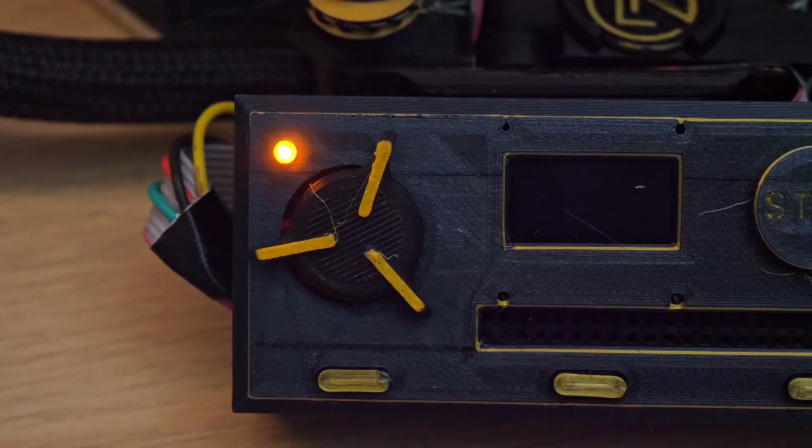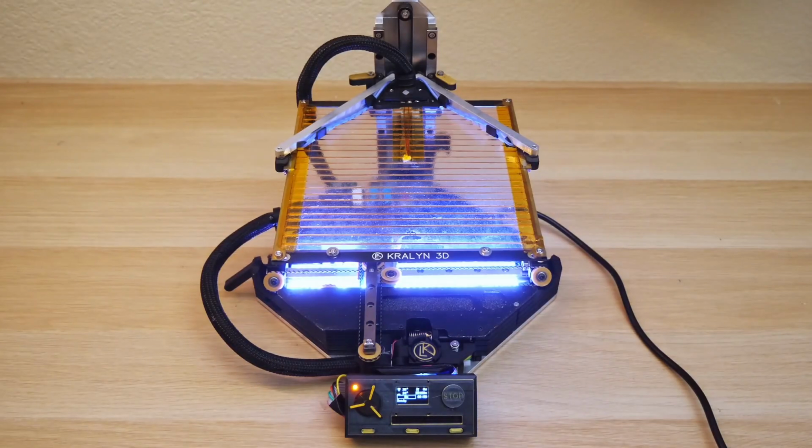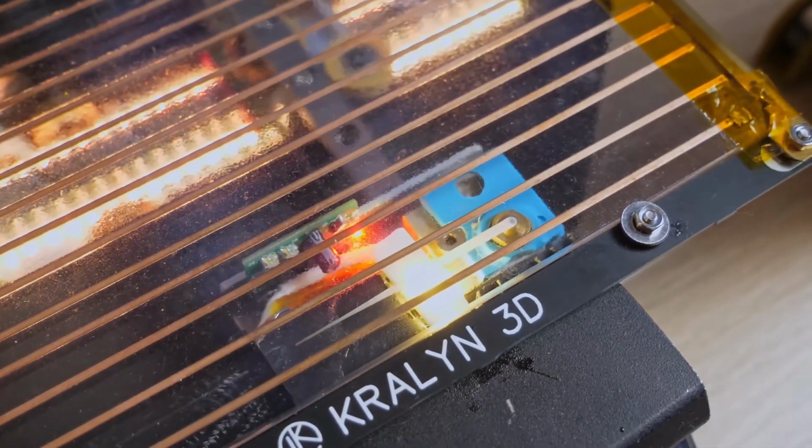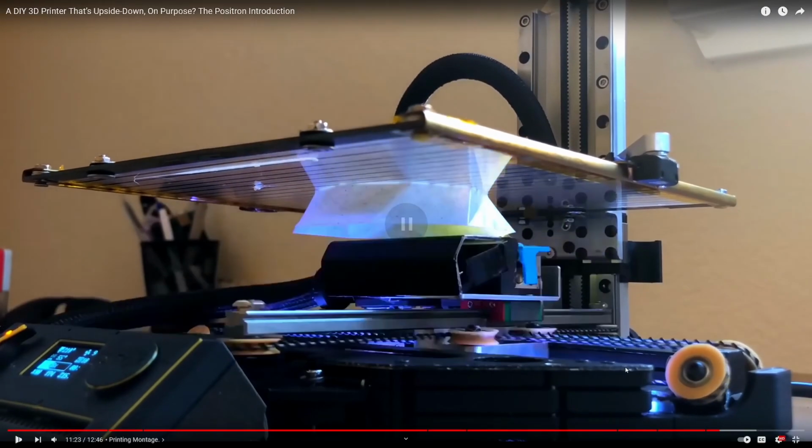So now the next question is, how many marathons has he done with this? And any sort of other design issues, or any sort of other safety issues? Because there's a safety issue. You have this guy open and you're touching the back of this glass, you're going to burn the heck out of yourself. So how do you handle that with safety? Also, no enclosure, and these parts are kind of exposed to moving parts, pinch hazards, get the cable stuck, your finger goes to a pulley, these things. So a lot of things here are not covered with any safety covers or anything like that.